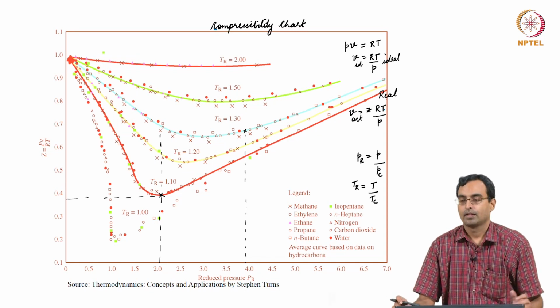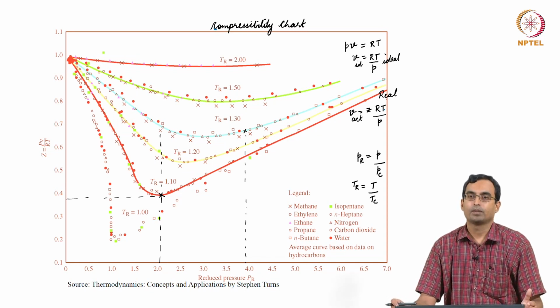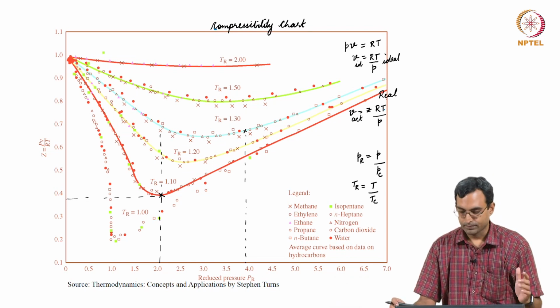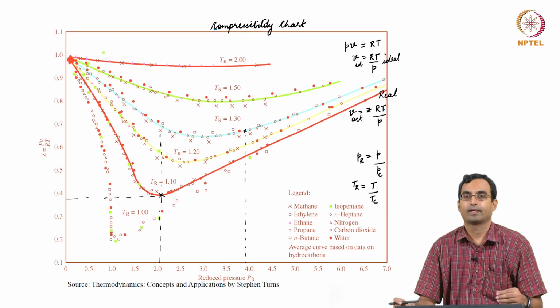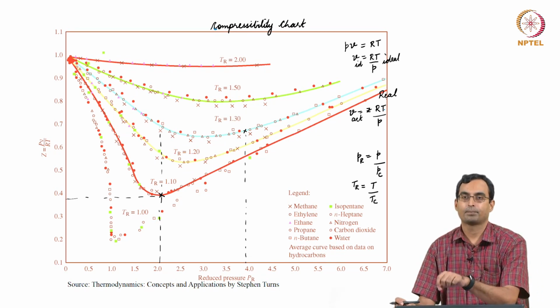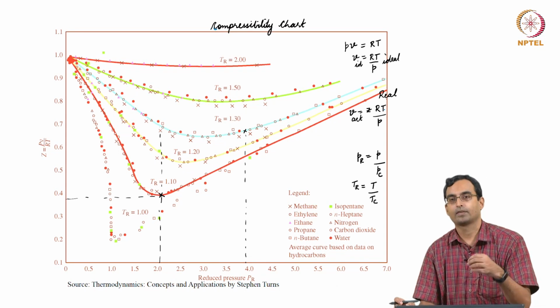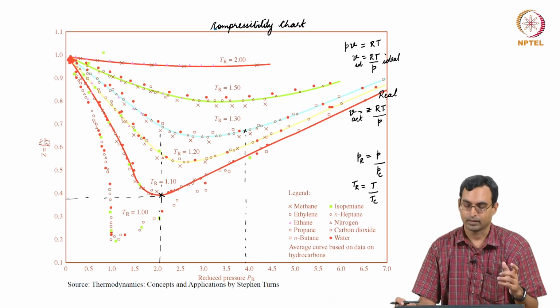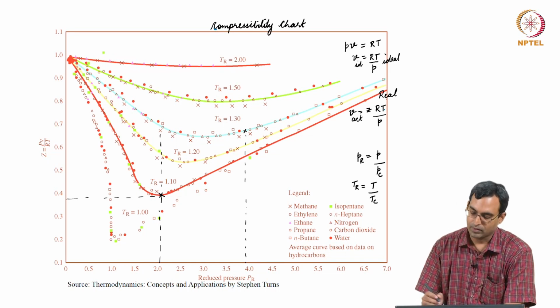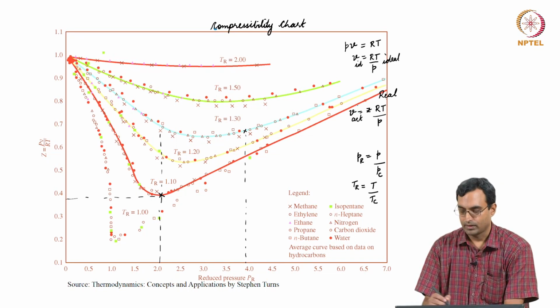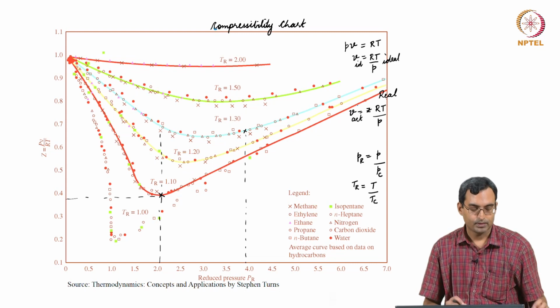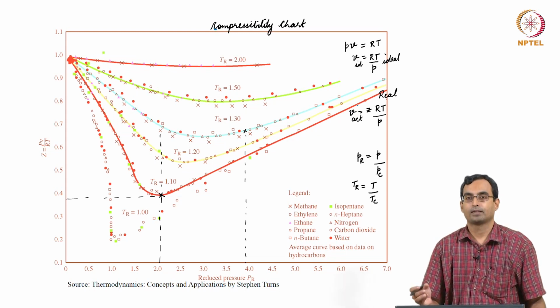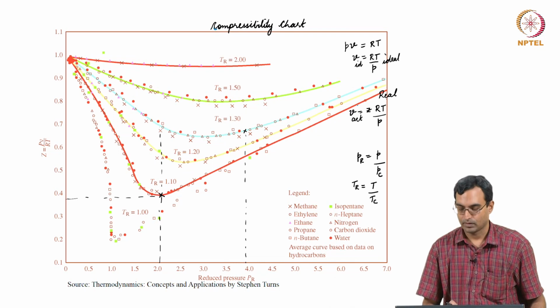In addition to this, another way in which we can deal with this is by using what are called tables. So, I can have gas tables for a specific gas. For example, I have air tables, I have nitrogen tables and so on, which would give me properties. So, in those tables I can look up the table for a certain pressure and temperature and find out the volume, or I can look at it for a certain volume and pressure, find out the temperature and so on. So, here also I can do the reverse. For example, if I knew the volume, I can find out the pressure and temperature from this chart and so on. So, I can use those values to calculate in problems and get better estimates than if I was to use only the ideal gas equation of state.